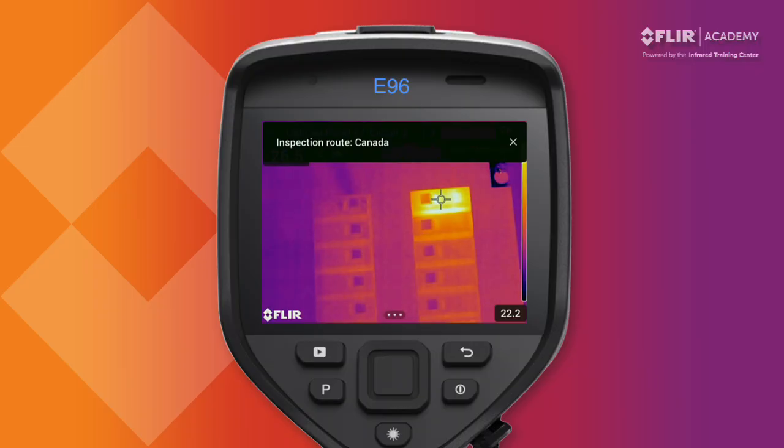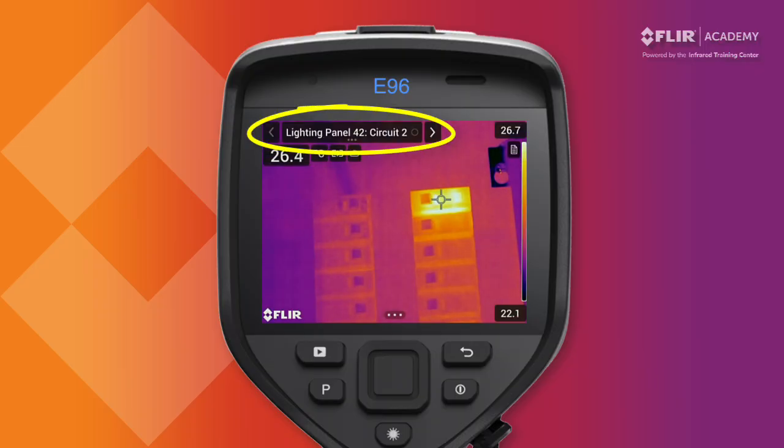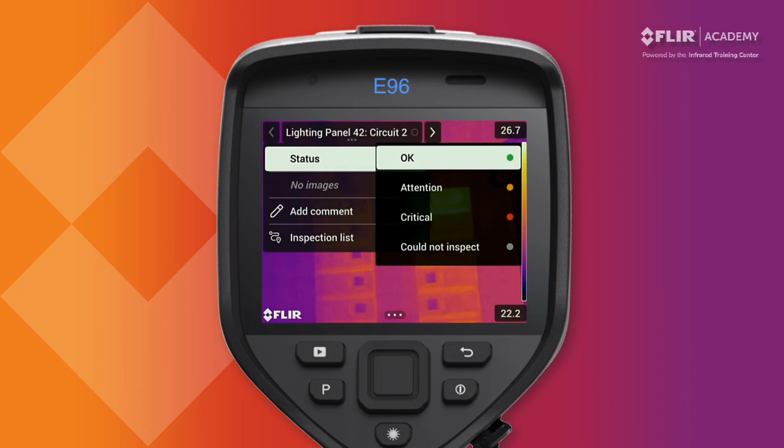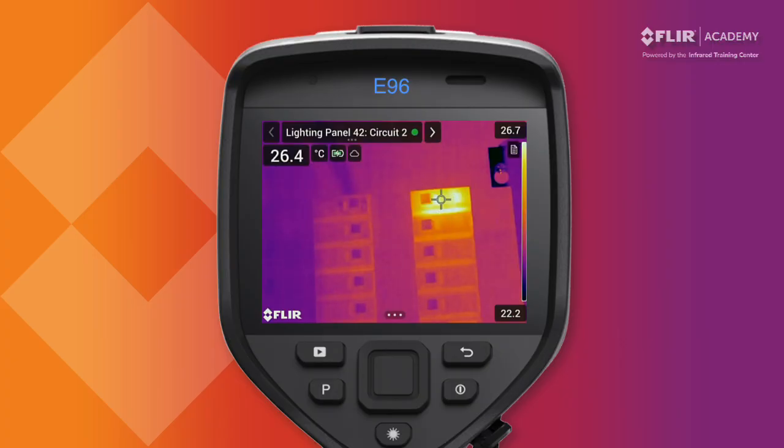Let's start with our first asset on this route, which is Lighting Panel 42 and the inspection point, Circuit 2. Any special instructions or notes for this particular inspection point can be found here. Tap the notepad icon to open and review. The spot measurement tool can then be moved over the inspection point to measure its temperature. Next, click on the asset name and the corresponding 3 dots to display the status options for this inspection point. In this example, we will mark the asset condition as OK and save the image. Select the right arrow to move on to the next inspection point.